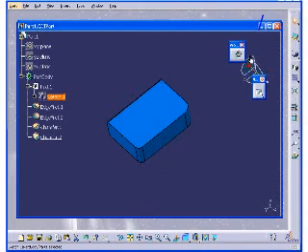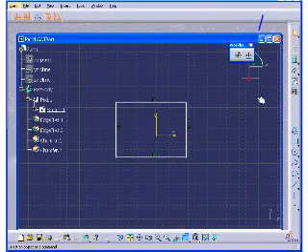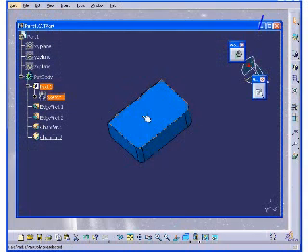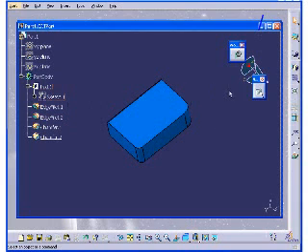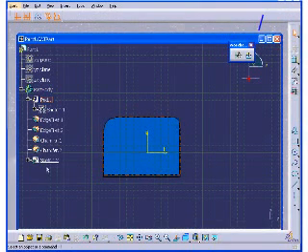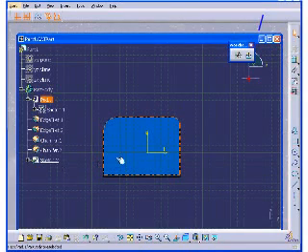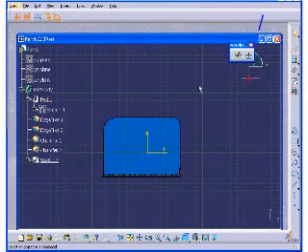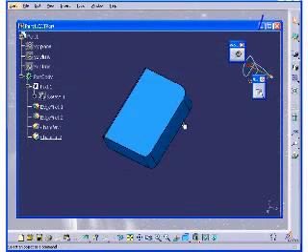Okay, let's exit. We can also create a sketch right on top of this surface. Oops, let me exit it. Sketch 1 was selected. Let me just click and deselect it. And I'll click Sketch and this face. And now I've created sketch 2. Now I can sketch something here and create a second solid. Okay, let's exit it.